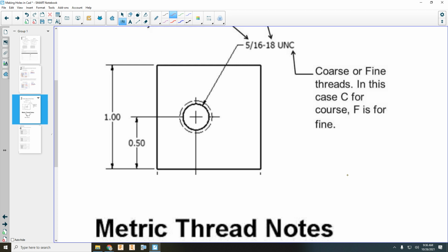Once you get below 1/4 inch, you can have a size 0, size 2. They usually go by 2s, but you can find a size 5 screw. They go by numbers. 6. Usually you don't see 7s, 10s, 12s, and 14s.